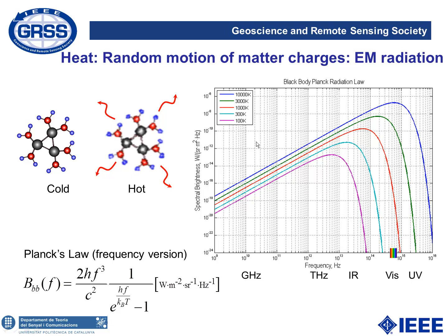You can see here that, for example, for 300 Kelvin, which is more or less ambient temperature, this radiation has a peak in the medium infrared region, but even at microwaves, this signal can be picked up by a sensitive receiver. This is interesting because we can measure the temperature of materials, and also parameters related to permittivities and roughness of these materials.